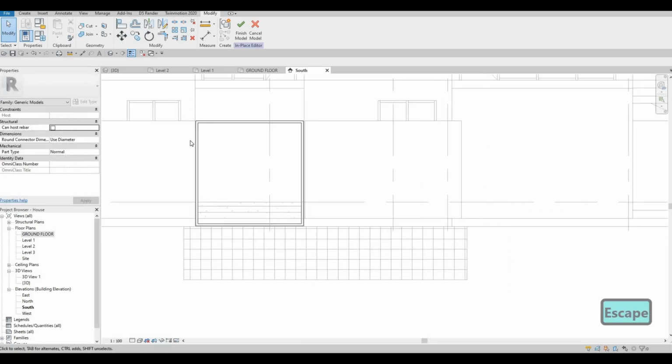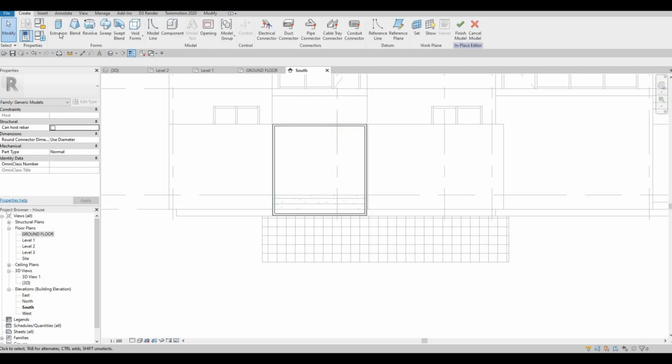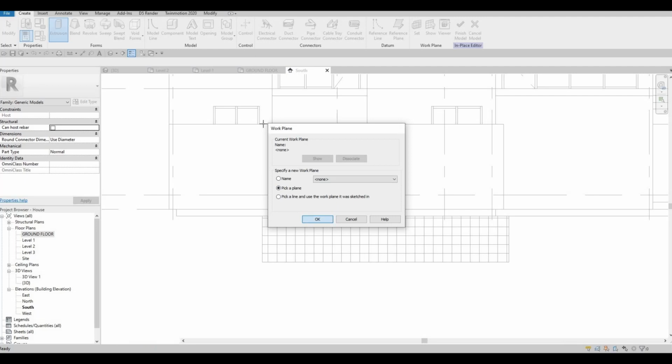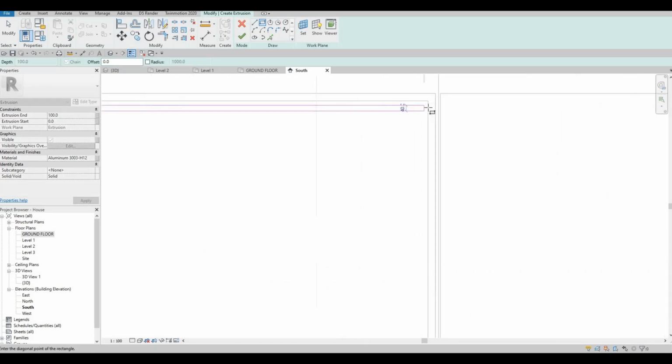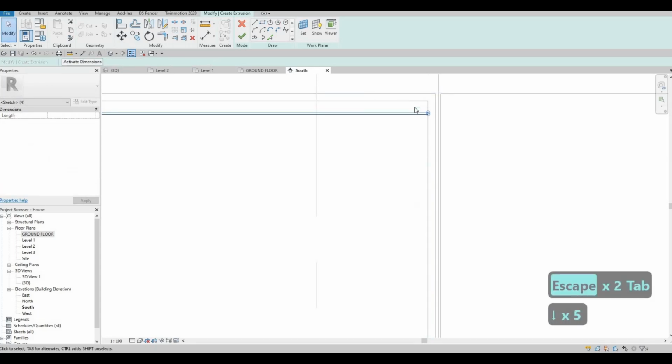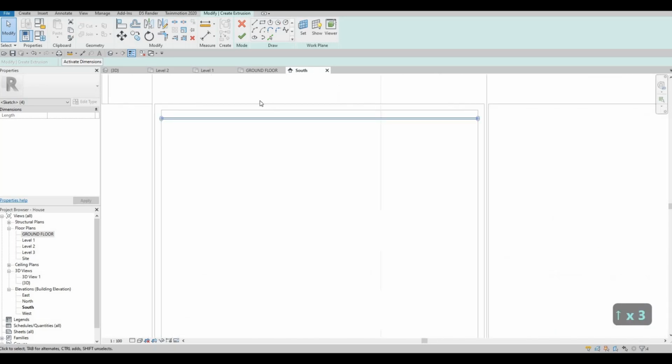So I want to change the look, so I'm probably gonna create a slanted or just a straight, straight horizontal grills. So I'm gonna create an extrusion again, pick a plane, and I'm gonna choose this one, and then here we need to create this thing right here, and then obviously it's too small, so I'm gonna give it something like that, so the gap will be good.